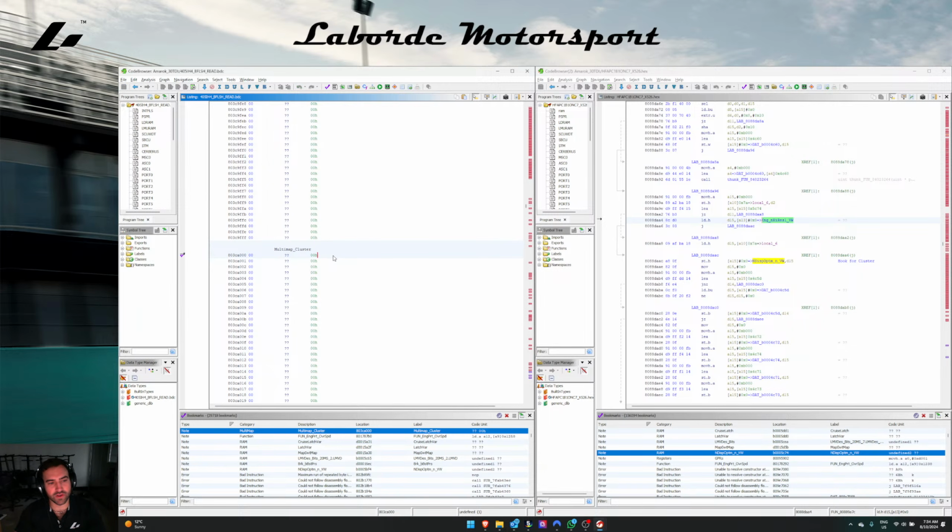Okay, so from here, what we are looking to do is pretty much create or load the preconditions. The first one, now it depends whether you want the person to be able to switch whether or not the engine is running or not. A lot of people have the precondition that the engine has to be off in order for the multi-map function to work. That's great, but it can be pretty annoying. Like if you just want to switch maps on the fly, you have to turn the engine off, you have to turn the ignition on to position 2, and then you have to start doing the switching from there. But I prefer it to be done anytime on the fly.